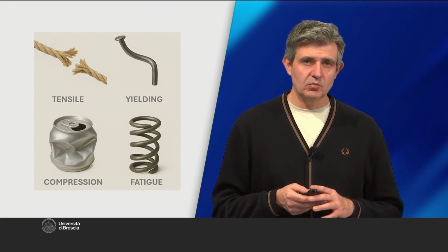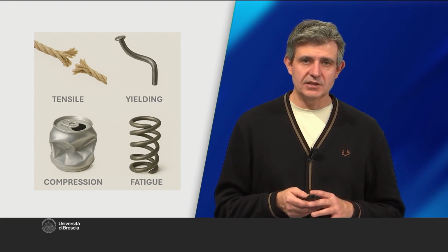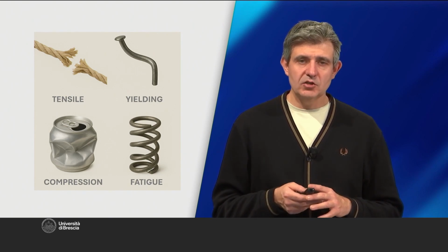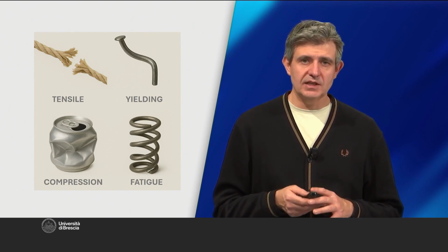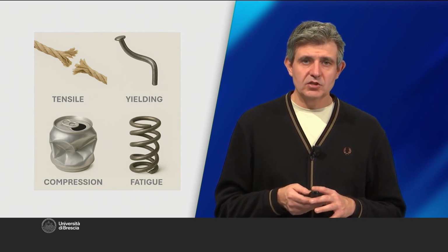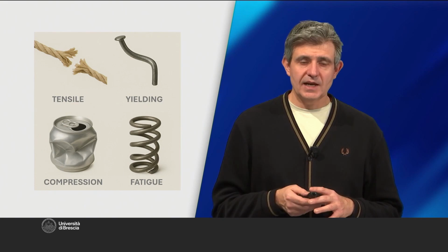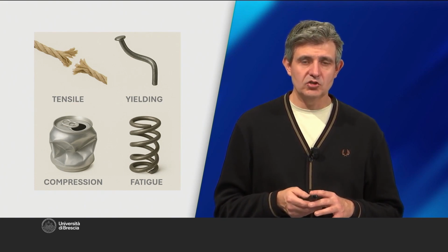In particular, we will refer to tensile strength in cases where the product is subjected to tension or bending and is able to withstand it without complete breakage. We will refer to yield strength when we want to avoid plastic, permanent deformation in a component, or when we want to ensure a greater safety margin.